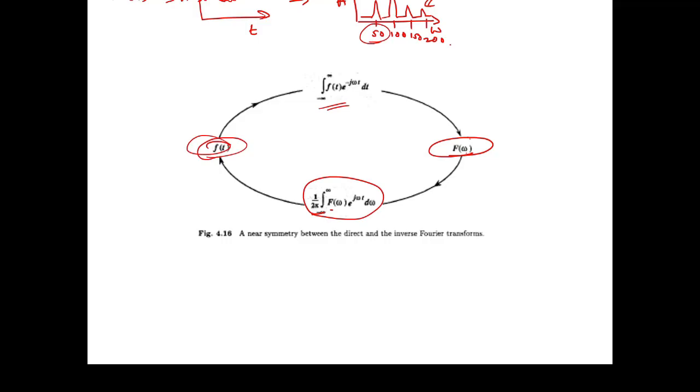So how do you ascertain what type of noise is there? In that case, when you do the Fourier transform, you will see that apart from the signal components, you also have an amplitude at 50 hertz. So from there, you can say confidently that this signal is corrupted with 50 hertz power line interference.